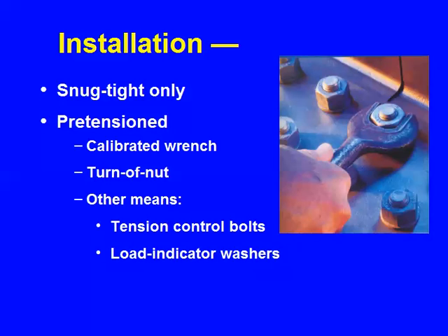So there's what's happening. That person has a spud wrench in their hand. A spud wrench is an open socket hex type thing with a pointy end. The pointy end is useful for spearing your buddy's lunch or lining up holes. Useful tool in bringing things into installation condition.